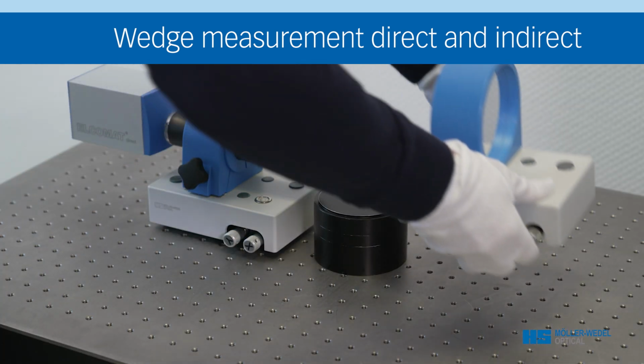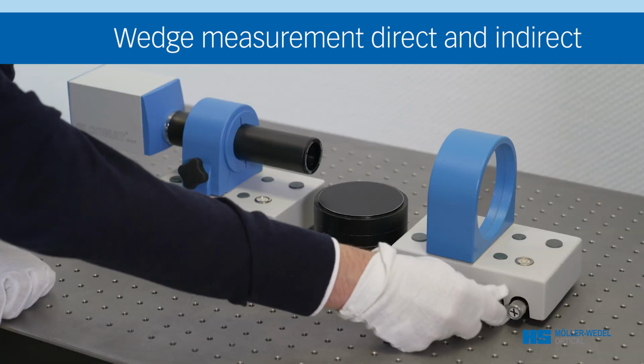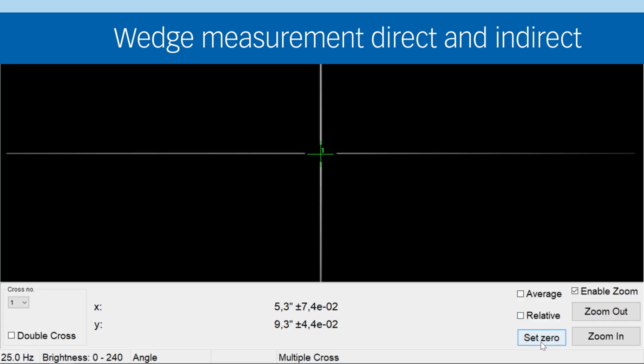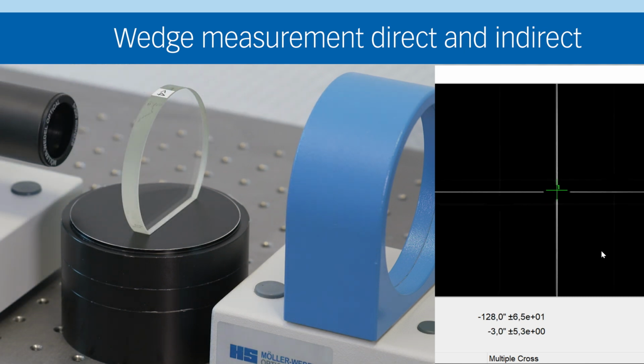For indirect measurement, the deflection angle of the wedge is determined with the aid of a mirror. First, the mirror and autocollimator are aligned, and the measured angle is set as the zero reference in the software. In the second step, the optical wedge is placed between Elcomat Direct N and the mirror. The display screen now also shows the calculated wedge angle.